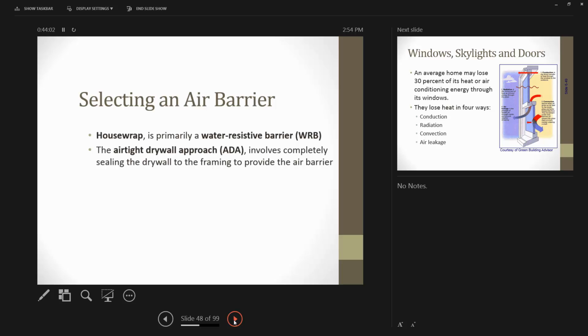and more and more as we start to get the buildings tight, building science is driving not so much anymore. We kind of went from having these leaky open buildings and air and moisture in and out in a fairly uncontrolled manner. In the name of efficiency, we went to really getting the buildings as tight as we possibly could, and that was probably the one that created the most unintended consequences, because we have this vapor drive that all of a sudden starts creating issues.